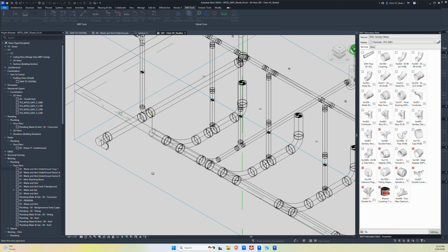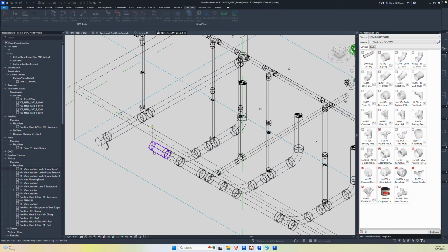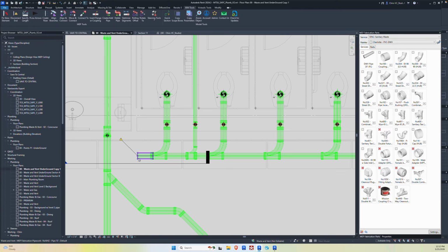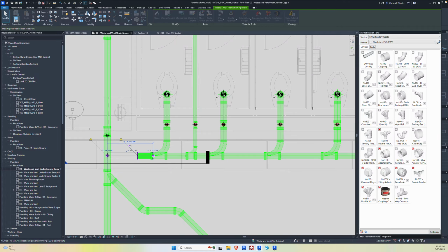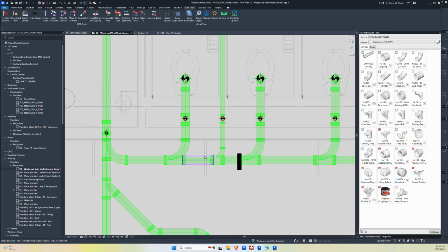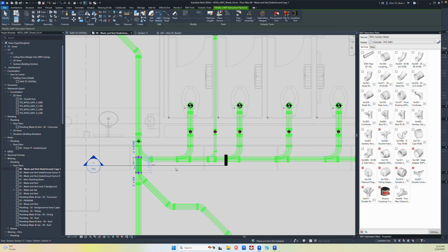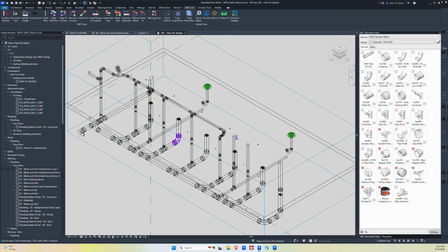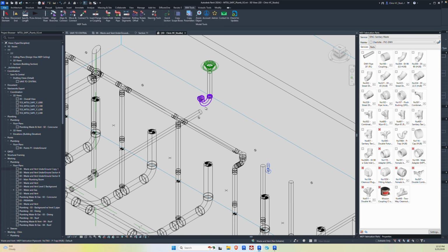So now we'll just hit the align branch. We'll come in here, we'll select a pipe, and we'll hit that. And then now we'll just go back and we'll drag this over and see how well that wants to work. And voila, we're there. We're still at an 1/8 inch. Everything moved, everything's at an 1/8 inch. Everything is great. If we go back here, you'll see that these traps got disconnected because fabrication traps are the bane of my existence because they're just nothing but problems. But we have a solution for that.